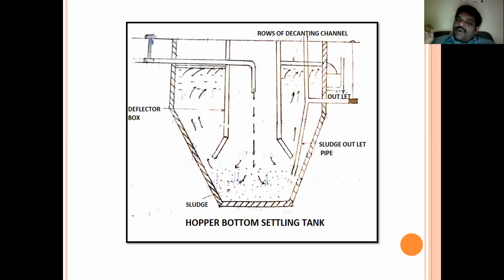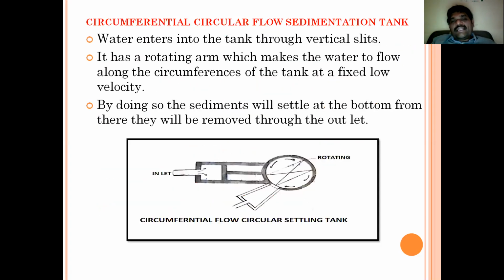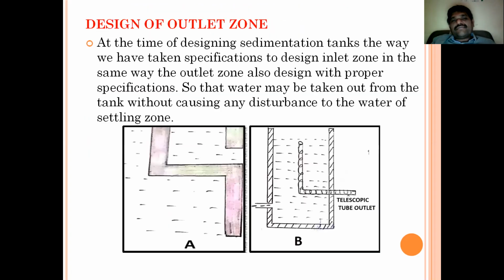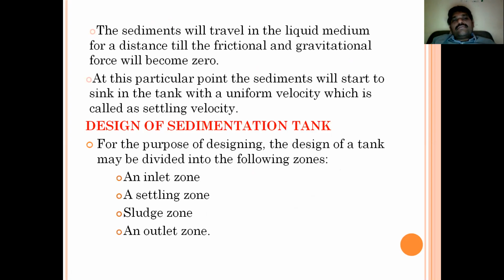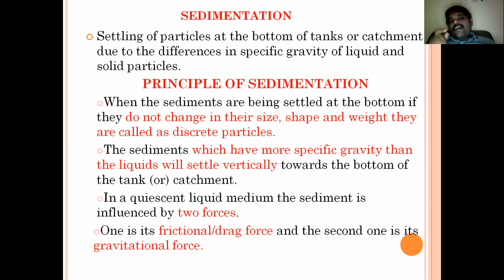We are discussing sedimentation. What is sedimentation? Removing of particles. We have seen the technical definition also: settling of particles at the bottom of the tank or catchment due to the differences in specific gravity of liquid and solid particles. Settling of particles, why? On what basis?